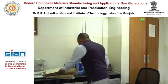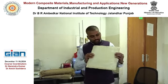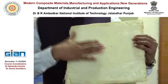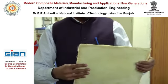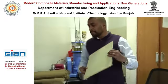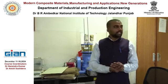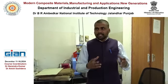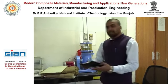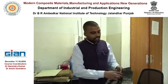So when we are producing, let's say this is one of the composite materials we have produced. In this composite material, the matrix should be continuous inside this particular composite structure. But actually it doesn't happen. Ideally it should be continuous, but actually, because of the limitations associated with our techniques, for example, we are using the hand layup technique. In the hand layup technique, what we do is simply take the reinforcement, for example, if this is a plain woven fabric or any other, this is the twill woven carbon fabric.